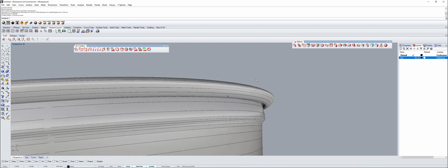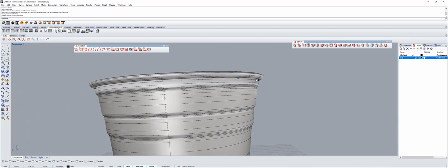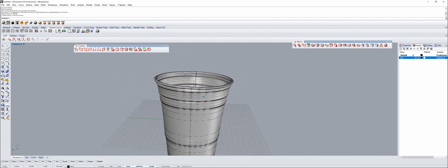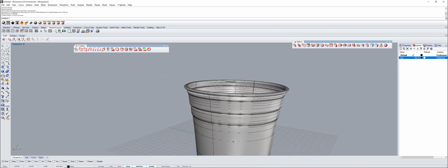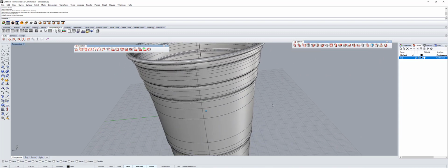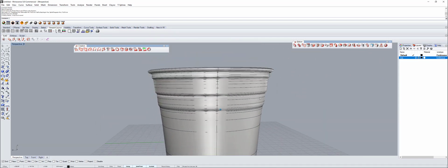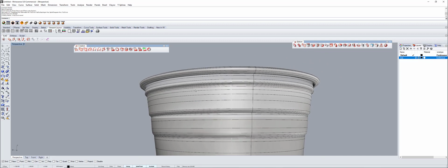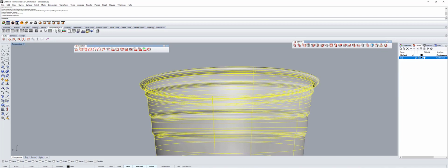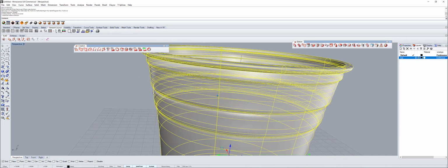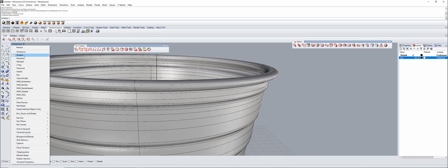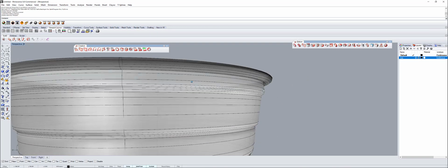It's not a solid. So if your plans are to print my cup, because you don't like it but you want to print my cup, it's very easy, guys. We're gonna convert this surface into a solid just using another magic command of Rhinoceros. So select your surface over here. I'm gonna show you first in ghost mode that this is just a surface.